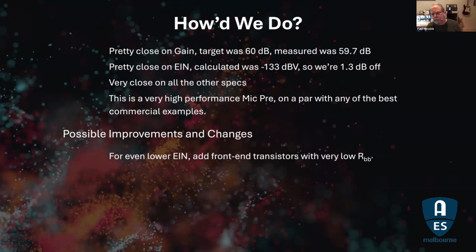I say fairly easily, having run into all kinds of problems with that, because these sort of op amps also have an enormous amount of gain, and you add some more gain in front of that, and what you tend to make is a nice oscillator.